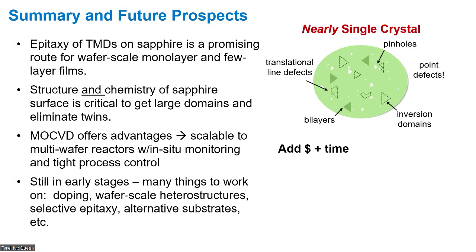So MOCVD is obviously more in line with a wafer-scale manufacturing process. Does there need to be another iteration of this lift-off technique to get it to that level? Yeah, there are places like IMEC working on it. There's been a lot of work on wafer bonding methods, to bond together dissimilar materials. Not that this is exactly the same, but you can use some of the same wafer bonding techniques for this layer transfer process. So that's an approach that's definitely under development.